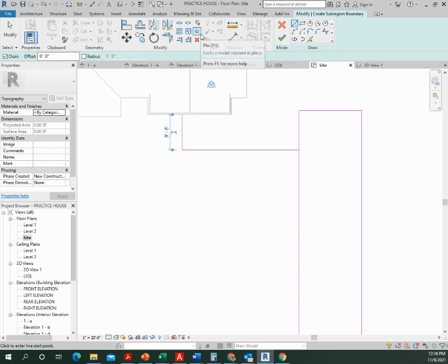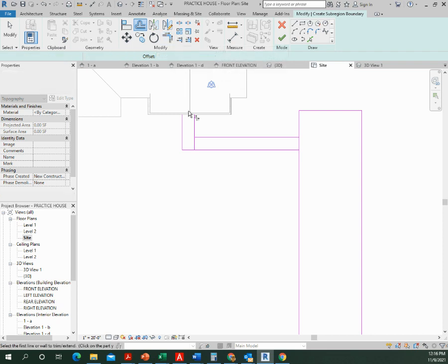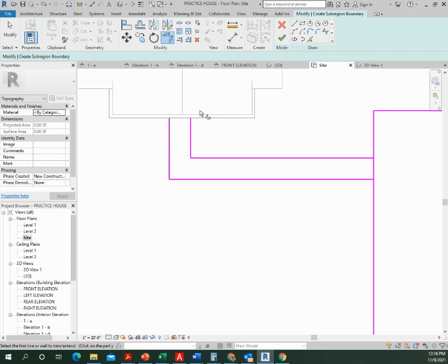And you can always use the offset tool. And I'm gonna make that 3 feet. That and use trim. I'm kind of guessing where the opening is, but it's more toward the middle. So I'm gonna go off of that, and I'm gonna close it up right here. In fact, let me draw a line here instead. So I'm gonna draw a line there instead, and I'm gonna use the trim tool